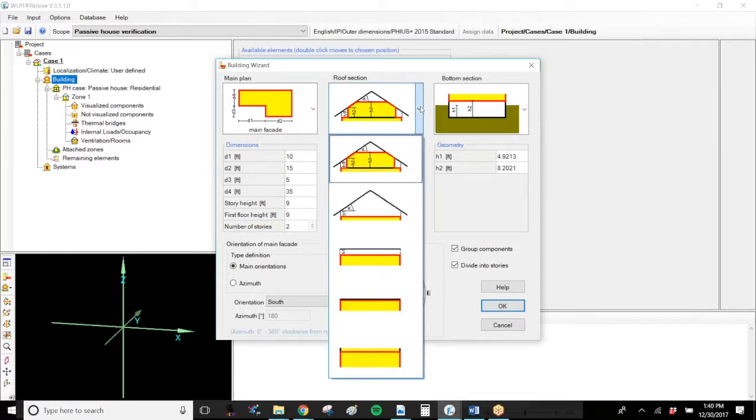The roof geometry, now you get to select if it is a heated attic versus unheated attic versus a vented flat roof, unvented flat roof, going down the line here. And then the bottom one is if you may be modeling a unit with heated space above it that's not part of the thermal boundary. So you can see they're showing the red lines as the thermal boundary. So this would be a heated attic, and then here the thermal boundary red line is cut off before the attic. So it would be a vented attic condition, etc.